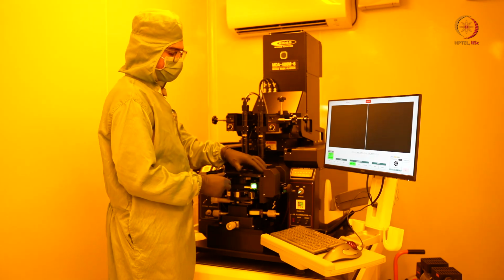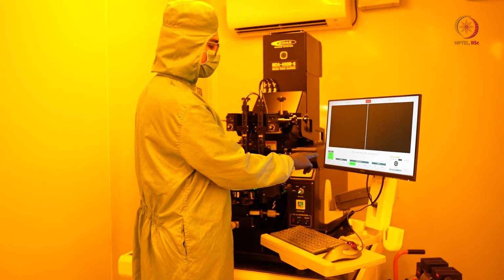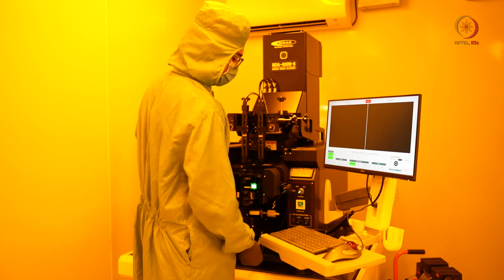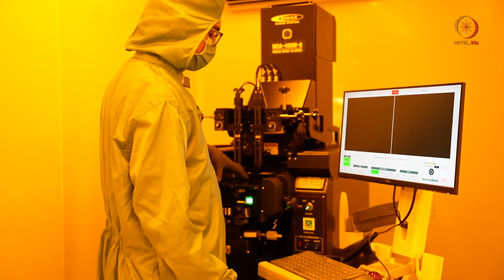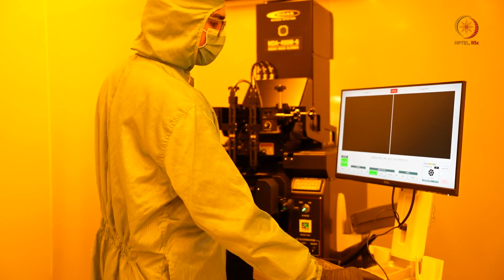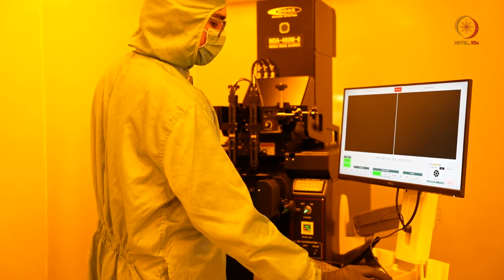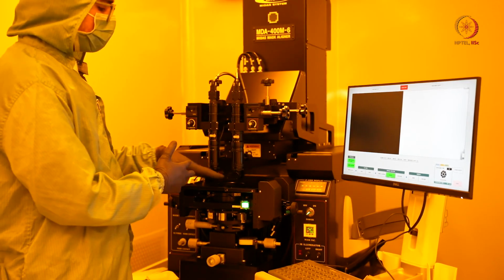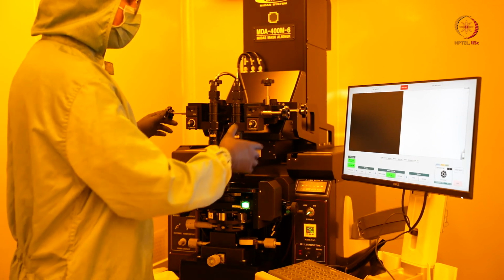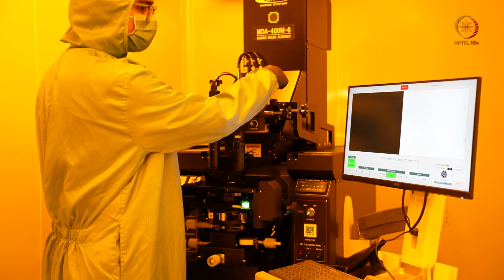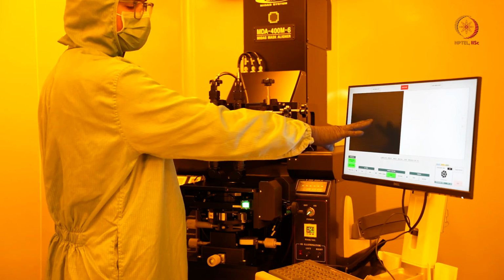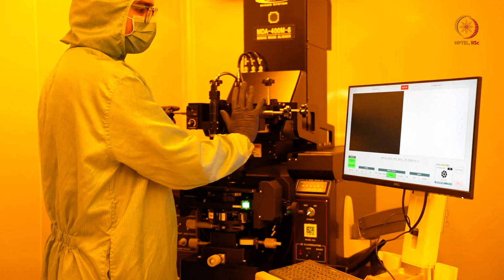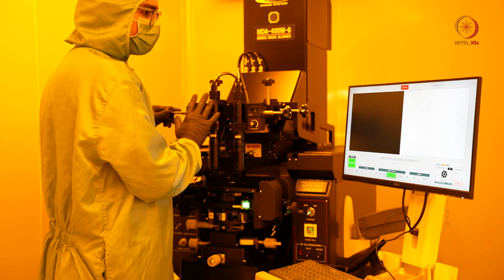So it automatically locks here, and you can see it on the green button here. Now what we can do is align the wafer and the mask, for which we will go to the alignment mode. When it goes to the alignment mode, you can see that the microscope comes and aligns with the mask here. So now you have to adjust the microscope so that you will be able to see the features. Now you can see there is a dark area here and the white bright region here. So this is the right microscope that you see here, and the left microscope that you see here.